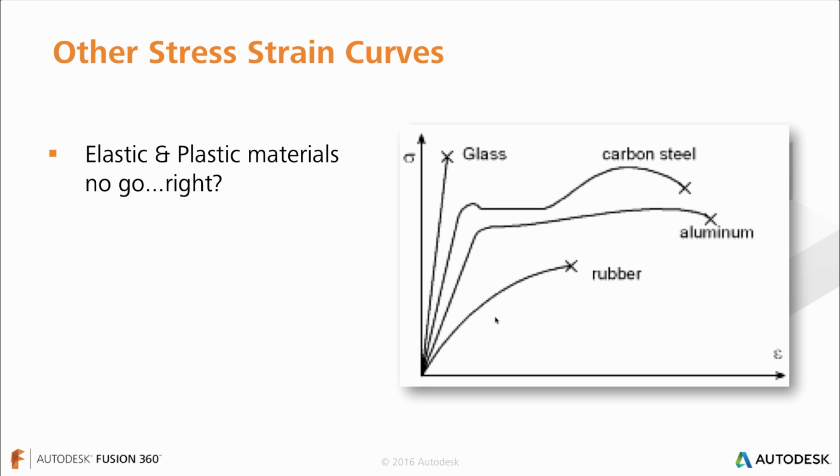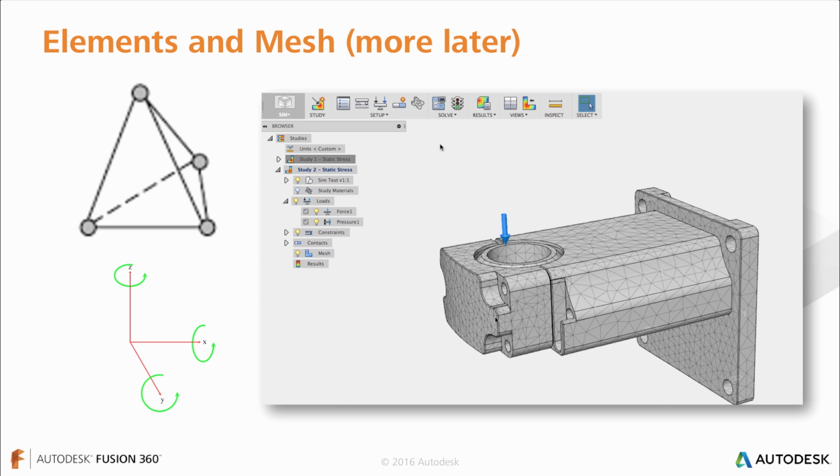Depending on what curve you're using to fit to that stress strain curve, you could minimize the error you might expect. When I say you can use it, I would recommend using it just to learn about how your model behaves. I think that's the most powerful way to use these simulation tools and finite element analysis tools. If you compare 5 different designs, all made of the same material, you can still get an understanding of relatively which one will behave better. Your results might not be empirically correct if you were to run the same analysis in the lab, but you're going to learn a lot of information about how your model reacts.